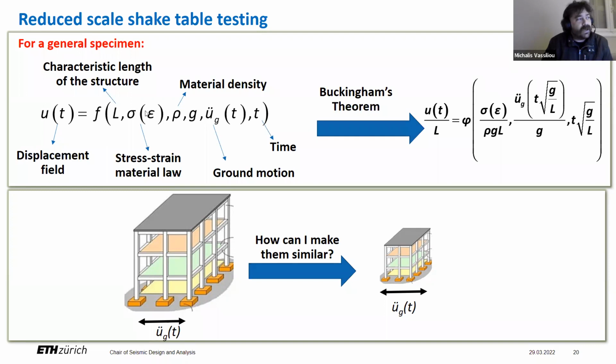by, I wouldn't say, it's not correct to say as many units as you have over here. It has to do with the rank of the dimension matrix. But often these two coincide, how many units you have and the rank of the dimension matrix. You see that all these are non-dimensional here. And this is a standard thing that people that have been doing structural testing have been applying.